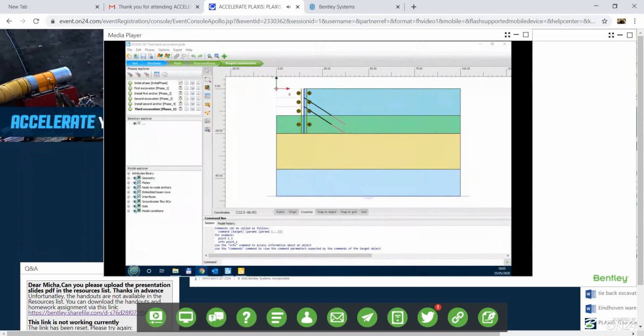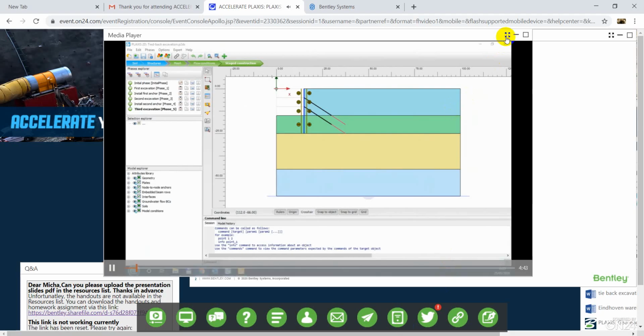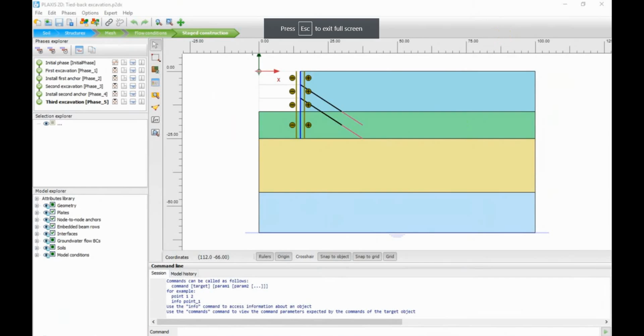And what we did here is that we made 4 soil layers using the Mohr-Coulomb model in all 4 of them. In fact, this model has the same sand over the full depth. The reason that we use 4 layers here is that Mohr-Coulomb has constant stiffness, and we want to simulate the effect that with increasing depth, we actually have increasing stiffness of the sand. I mean, the deeper sand is more confined, it has a higher stress level, and therefore the stiffness is higher. And Mohr-Coulomb doesn't take that into account in a simple way. So we modeled it here as 4 layers.